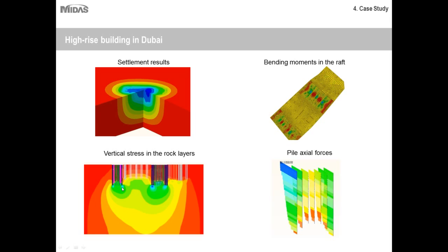And since they had used embedded pile elements, they defined a different interface for the tip and a different interface for the pile itself. And due to enhanced visual aids of the popular software available these days, you can visually verify the results whether the piles are getting mobilized or they are transferring the force correctly or not.